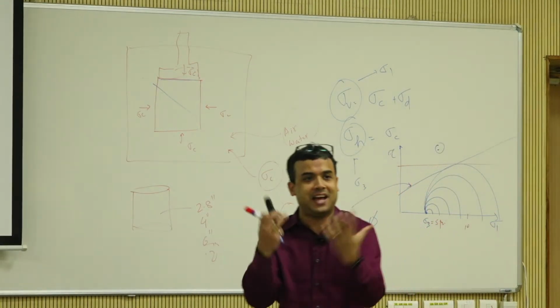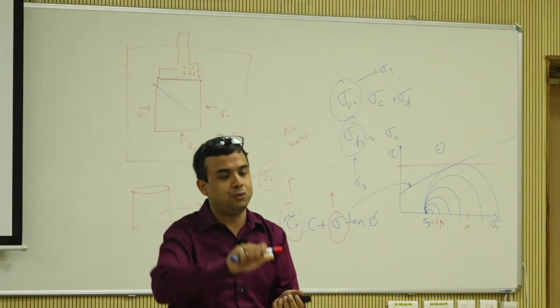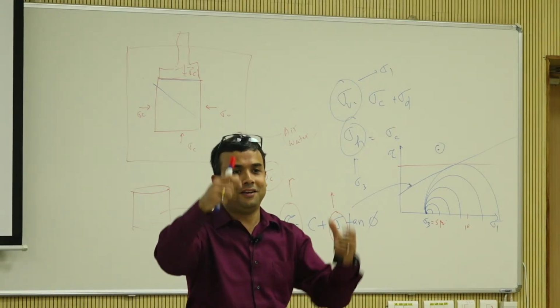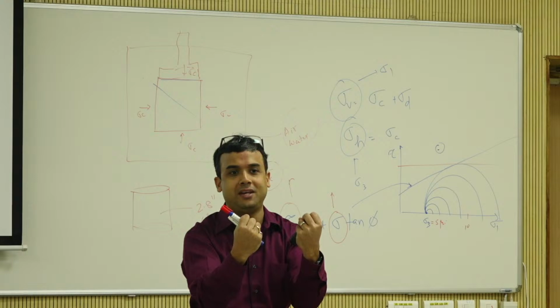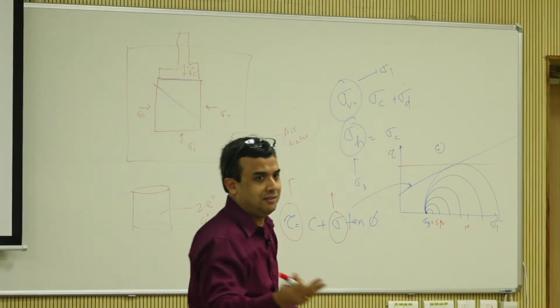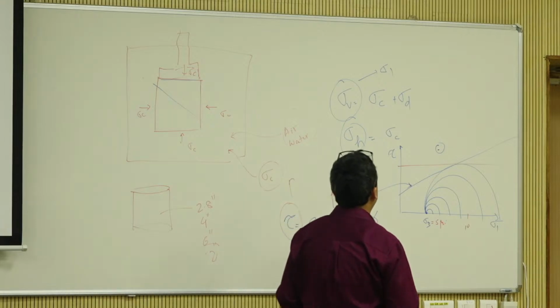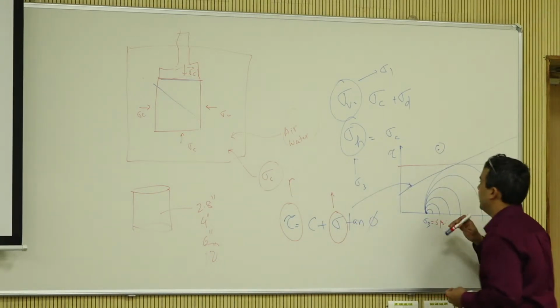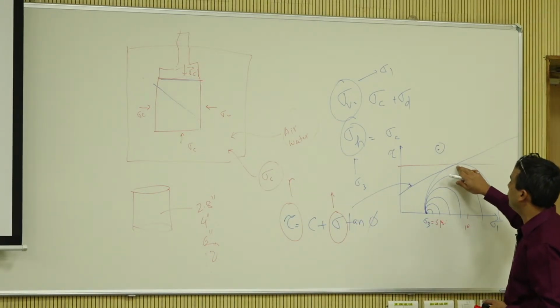So when you are applying additional loading, if you do it undrained, all of the loading is taken by water, so you're not gaining any strength. That's what happens, right? Consolidated, undrained and stuff like that. Those, so you'll see those behaviors sometimes.